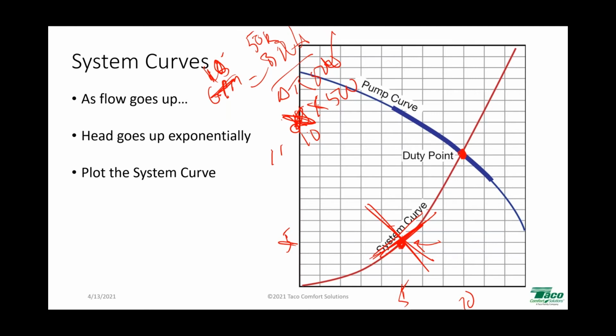All right, and that's why it's important to know that system curves do in fact exist. Because again, I do a lot of work to figure this out. Otherwise, I just slap whatever my favorite pump is on there, let it go. I'm over pumping, and I'm limiting the efficiency and economy of operation of the system. Let me know if that makes sense to you, because this is so common out there in hydronics.